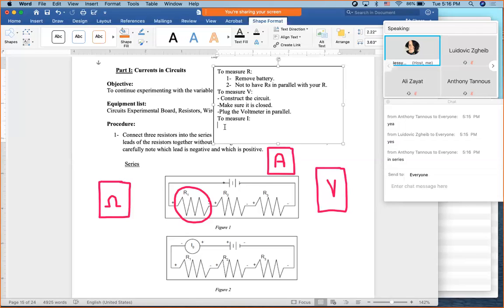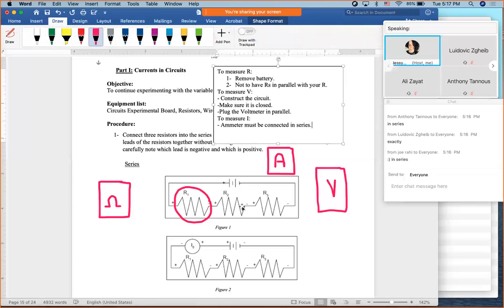Every time we have this experiment in the lab, the students end up burning the fuses many, many times on each bench, and all I do is change the fuse. So yes, the ammeter must be connected in series. And to be honest, to do a series connection, you're supposed to open the circuit like that.